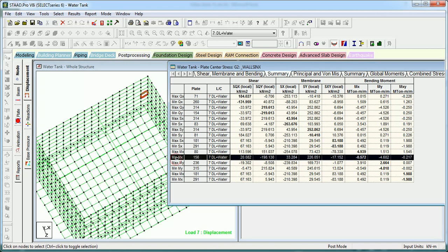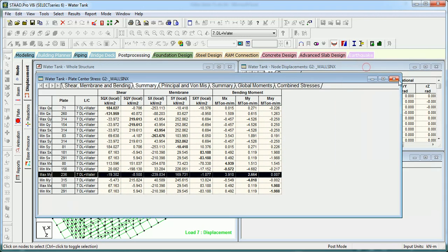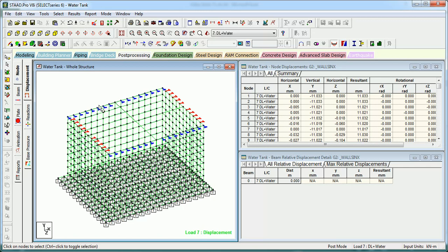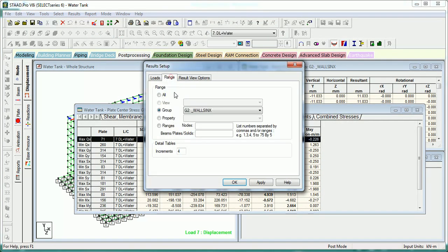Minimum is minus 0.4 at the center. That will be the outside moment. As I guess, as we are modeling subgrade, the behavior shall not be same as we think of fixed bottom and pin top. You can check the moments of Y direction walls too.